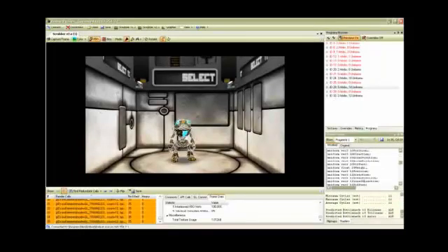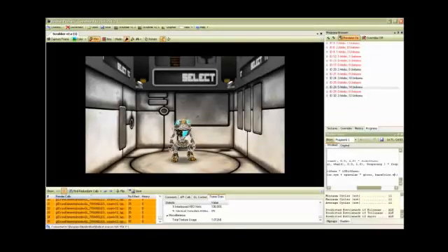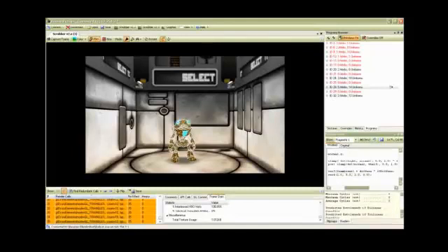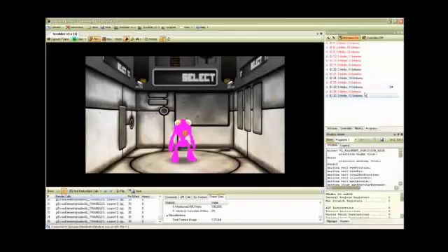The interesting thing about that, as I mentioned, is that not only can you view it, you can actually modify your shader and load it to the device in real time. So I'm going to go ahead and do that here. What I'm going to do is replace the final color that's calculated with just a solid color. So I'm going to change this so that it's just writing out fuchsia. And if I switch that, you can see in the scene now the robot's being drawn that way.